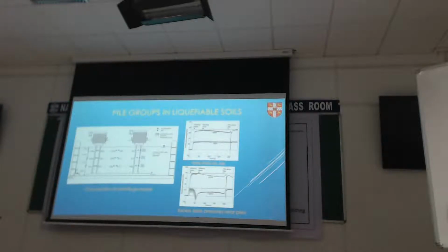But what's most intriguing for me is this one, this guy, number 10952 or whatever you call it. This pore pressure transducer is next to the pile of the heavily loaded one. You can see as the pile is trying to go away, it's generating that suction. In fact, it has gone to absolute suction.